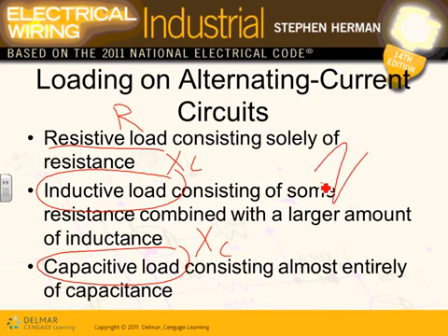The impedance is made out of three components: the resistive, the capacitive, and the inductive component. All these components make up the electrical load, and because of this, it will create a power factor, an angle between the current and the voltage, which if it's large enough will screw up the power system. It will pull more current than what it's consuming.